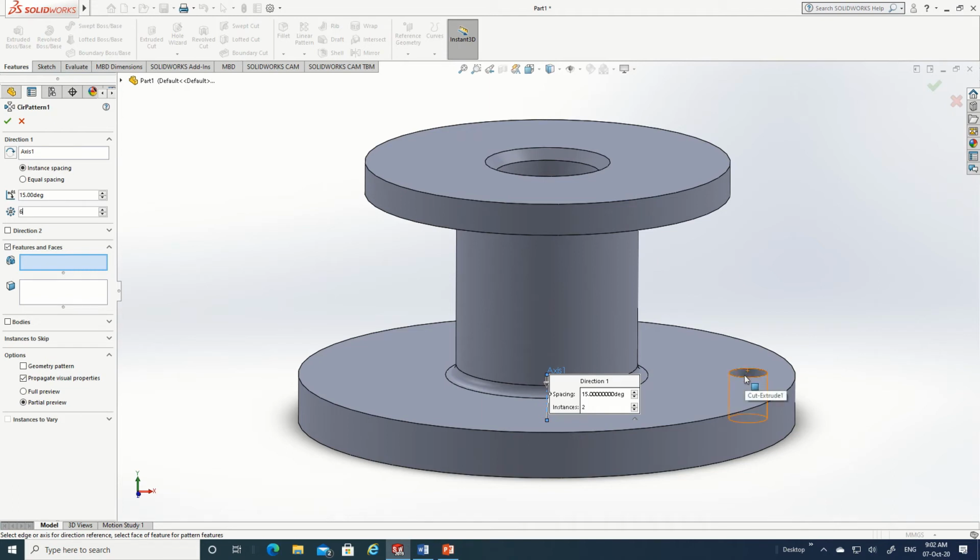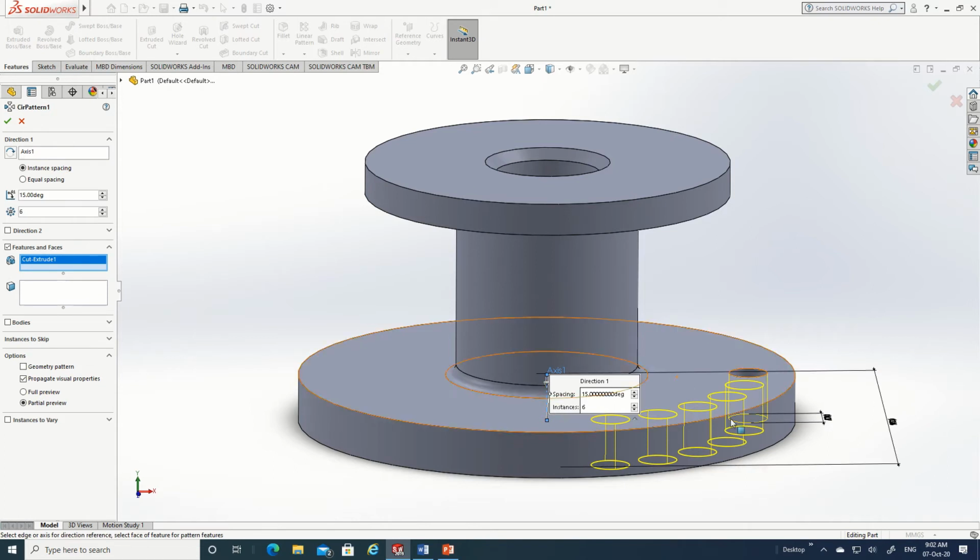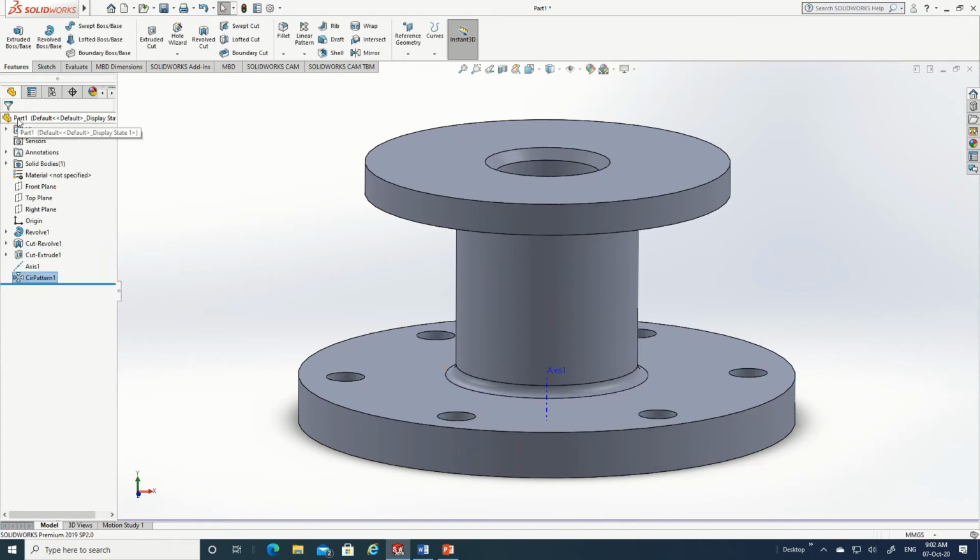Go here like this. Click. See? So how many has it made? At an angle of 50 degrees, it has made. So go here and make equal spacing. If you click on the left side, equal spacing, it has done it completely. Okay. Now you have got 6 holes. Say yes. Now you can very clearly see there are 6 holes with us.